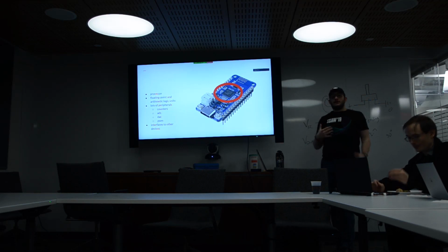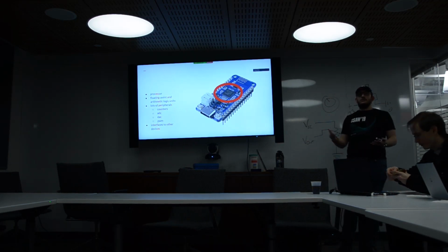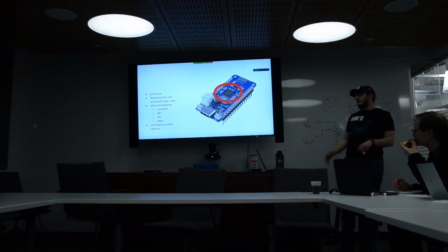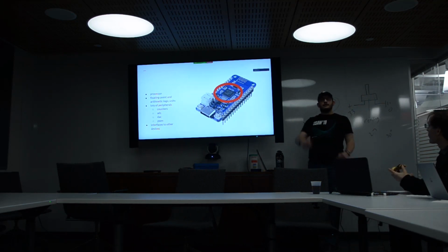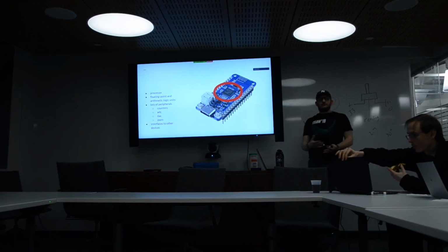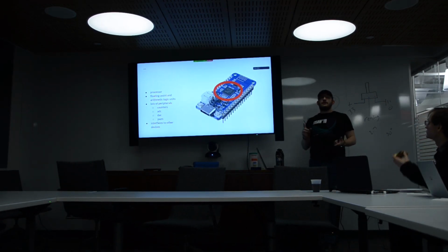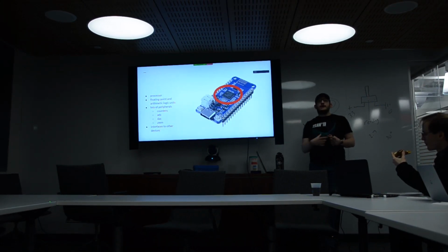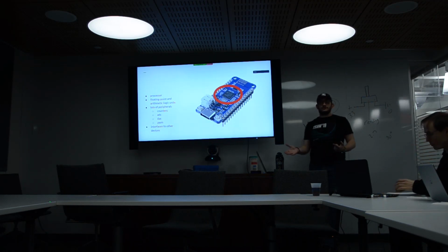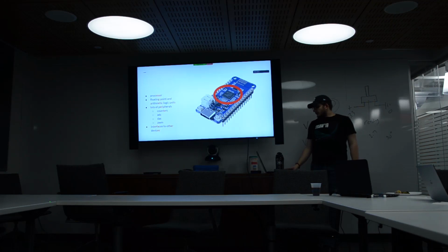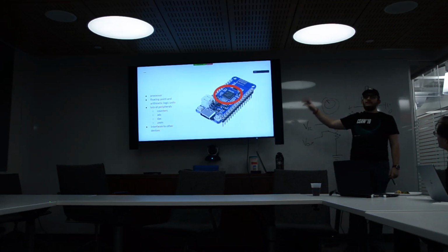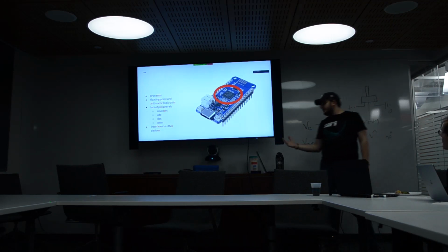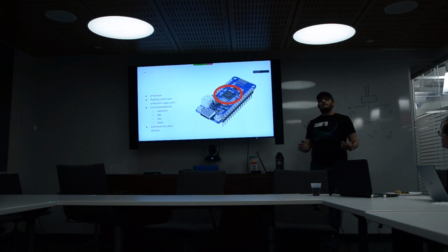So if your entire processor runs at 3.3 volts, but you need 2.2, for example, you can do that with PWM by turning a 3.3 pin on and off really, really fast, and the apparent voltage will be 2.2 volts, but that's crappy and not good enough for doing audio, for example. But a digital to analog converter has a much nicer method of getting a good, stable voltage out. Going back to the microcontroller unit itself, it also has the ability to interface to other devices over buses and things like that,